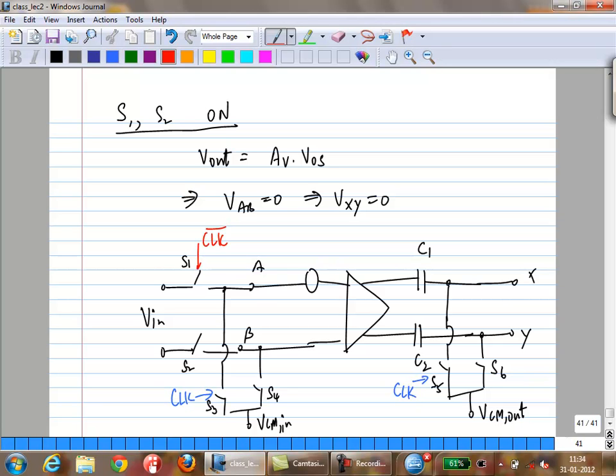Okay. So now what happens is, this thing is fine if you have, let's say, amplifiers with low gains. Typically, if you have amplifiers with high gains, what happens? Remember that the input referred offset is a fictitious quantity. It's like input referred noise, right? All the offset actually exists at the output. If you have high gain, so let's say you take a differential amplifier with large current and high resistance, the output offset voltage is going to be larger also.